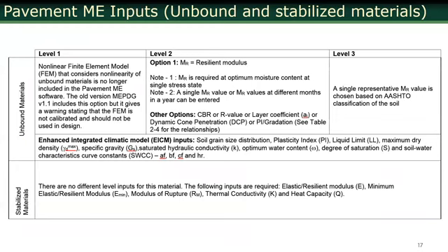Soils, their stress-strain response, and their modulus is directly related to the confinement level and how much stress they are experiencing. If they are nicely, tightly packed, their stiffness will be high. If they don't have enough confinement, their stiffness will be low. This is logical. Anybody in the soils area knows all about this. It's an important input, but unfortunately at the moment, it's not included in PavementME. And the reason is I don't think anybody came up with an efficient nonlinear model to do this.